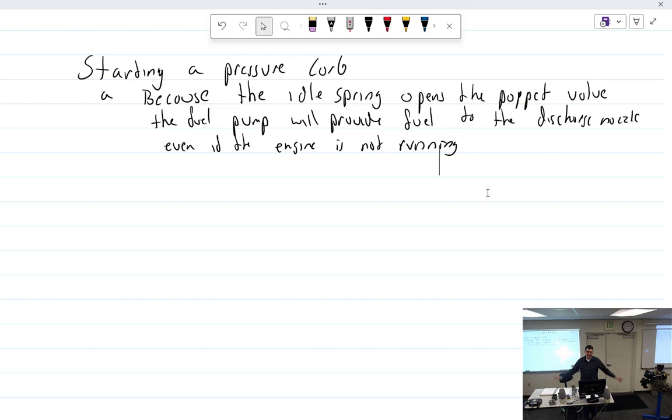That's it. Because when the pressure gauge shows pressure, I know that the pressure came off of the manifold up front. Talk about that next week. If I have pressure there, then I'm starting to get fuel to the lines. Then I'll go ahead and try and start it. Oh, so you just want a tiny bit of pressure. Yeah, you just want a tiny bit of pressure. I don't watch it like that. It's going to go up half a gauge, so I'll let it go maybe 1/4 of the gauge up. Just a good indication I've got positive pressure. Shut it off.